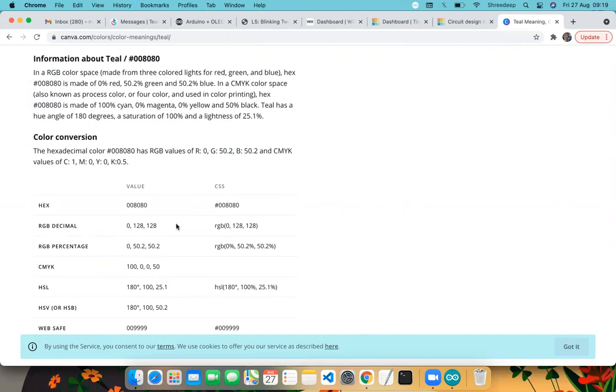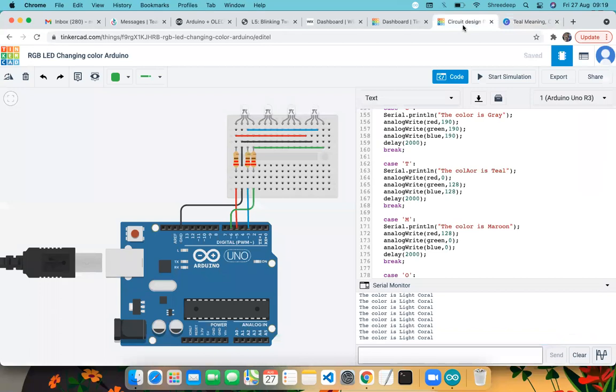Now the question is, how do you provide those color values, or maybe those sort of analog values, to the Arduino pins which are digital? Now see this tilde sign, these are actually PWM compatible, right? I think you have basic PWM knowledge. Do you know what PWM is and why it is called pulse width modulation, right? It shifts the duty cycle based on the voltage we are supplying.